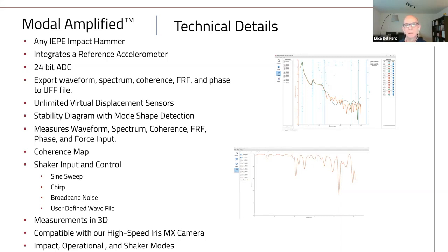But this takes a lot of time, because if you're in the field, you need to find a way to bump in the right way, and maybe your component is stainless steel. And so the problem is, how can I fix the accelerometer? Or if it is a small support, the support is so small compared to the accelerometer that it starts to be quite tricky to do a bump test.